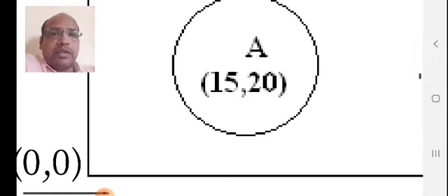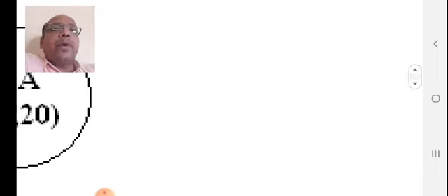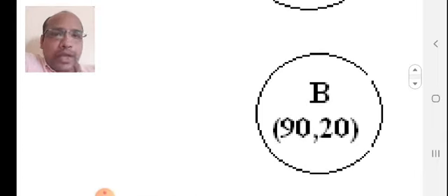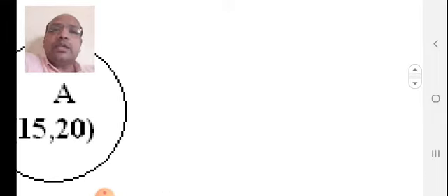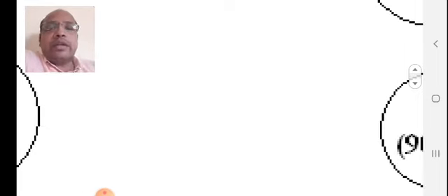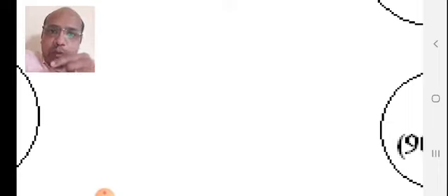This happens in absolute coordinate system, but in incremental coordinate system, you write the coordinates of point A with respect to origin, but while writing coordinates of point B, you should write the coordinates of point B with respect to point A. Meaning, while writing coordinates of the next point, the previous point should be the origin.